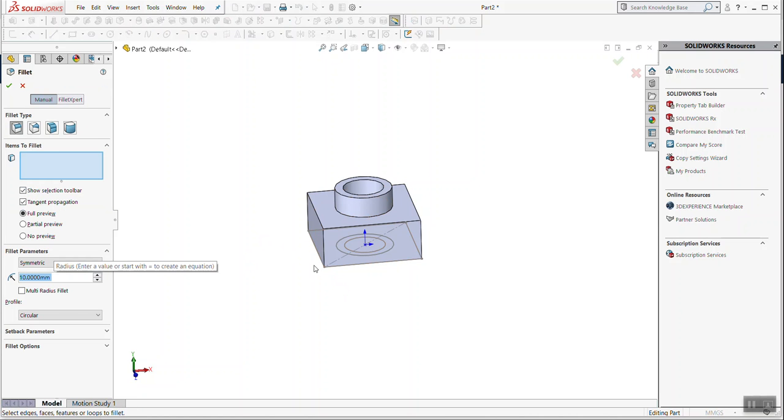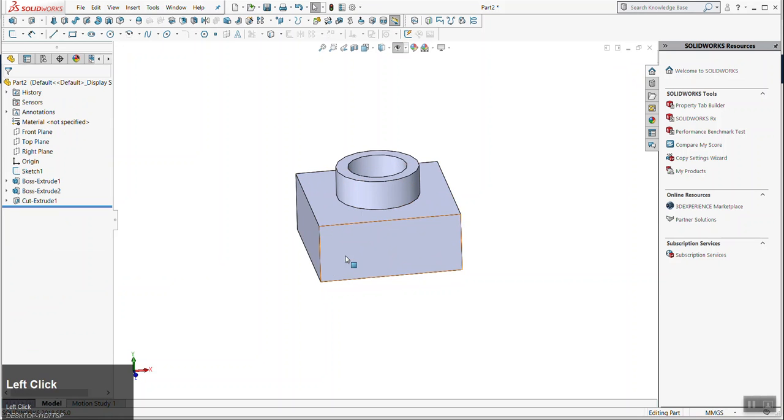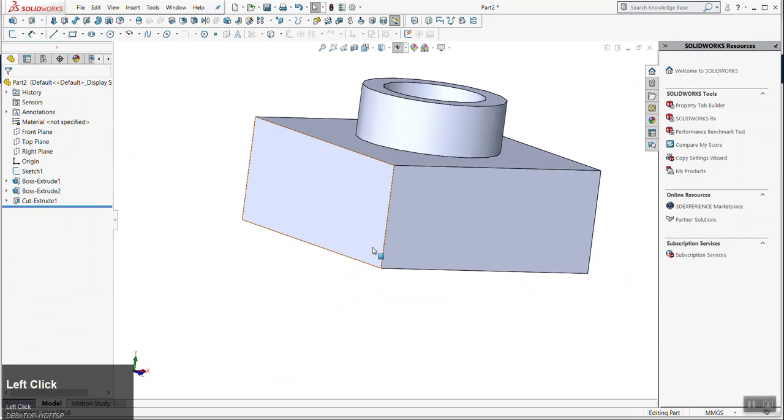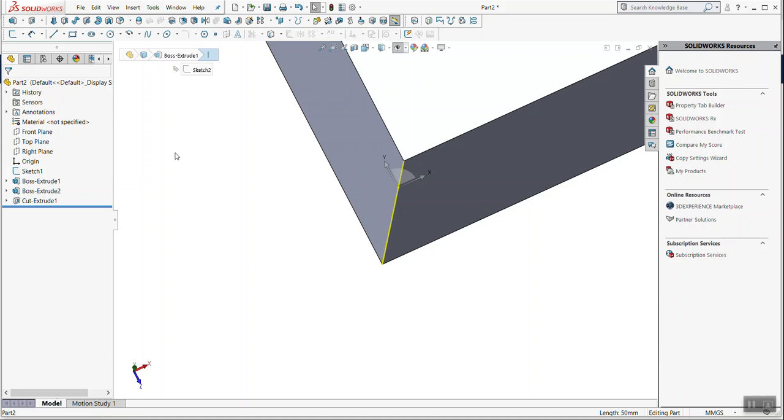the tutorial. A fillet basically says, hey, take this right angle corner, or I guess it doesn't have to be a right angle, take this corner and create a tangency between the two faces. And you're telling it how big or small to make that tangency. So with this language, these are faces, that's a face, this is a face, this edge is a corner. Tangency means, the formal definition is touching but not crossing, for what it's worth.